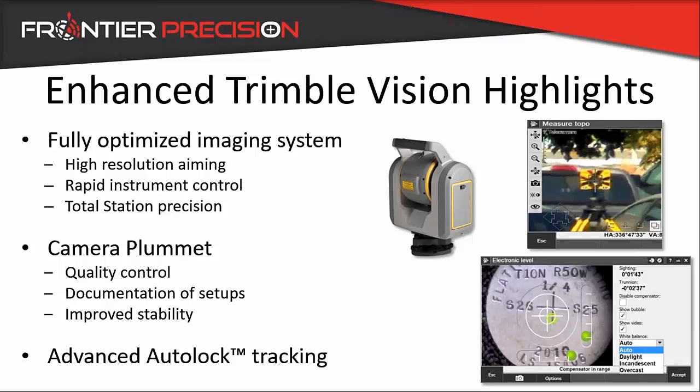There's also a camera Plummet, as you see here in the bottom right. That's the camera Plummet, so you can use a traditional optical Plummet as well, and I'll talk about that in a moment. But the camera Plummet gives you a couple of other things that you would not normally get. One, the biggest one being quality control, the ability to take a snapshot of that image and save it, and that actually shows how well you're over the point, your levelness, and then you'll see here in a moment maybe some other information that you'd want about your instrument setup.